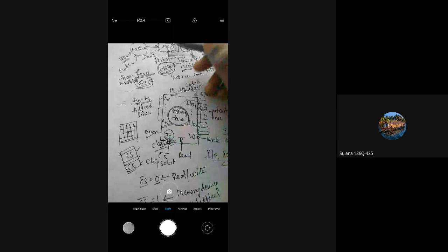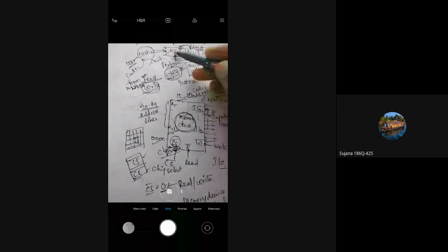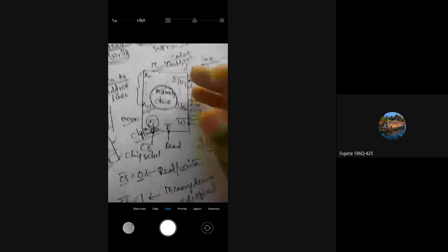Okay, so on this MPU unit's instructions, this memory device will not change its data, it will not provide the data, it will not take the data. So this memory gets disabled, and even though it is connected physically, it will not be able to access the data. So this is what this chip select pin is for.